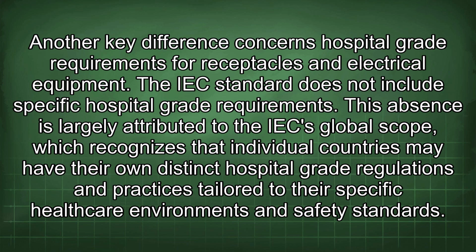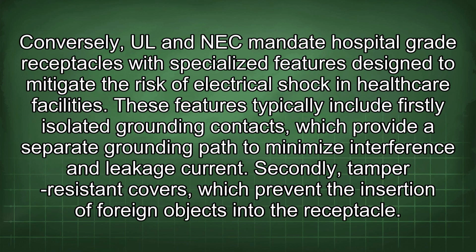The IEC standard does not include specific hospital-grade requirements. This absence is largely attributed to the IEC global scope, which recognizes that individual countries may have their own distinct hospital-grade regulations and practices tailored to their specific healthcare environments and safety standards. Conversely, UL and NEC mandate hospital-grade receptacles with specialized features designed to mitigate the risk of electrical shock in healthcare